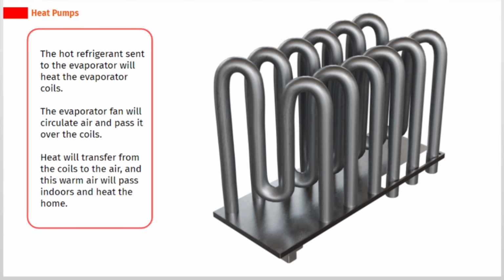The hot refrigerant sent to the evaporator will heat the evaporator coils. The evaporator fan will circulate air and pass it over the coils. Heat will transfer from the coils to the air, and this warm air will pass indoors and heat the home.